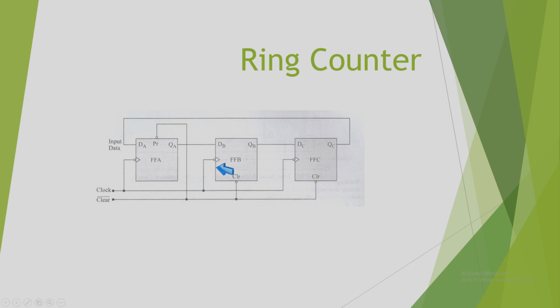All of these 3 flip-flops will behave in the same manner, and above all, they are negative edge triggered. You can see from this symbol, this is for negative and this is for edge triggering. So all of them will be waiting for a negative edge in the clock pulse. A common clock pulse is feeding all the 3 flip-flops, which means it is a synchronous device.